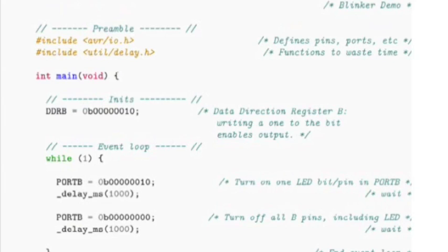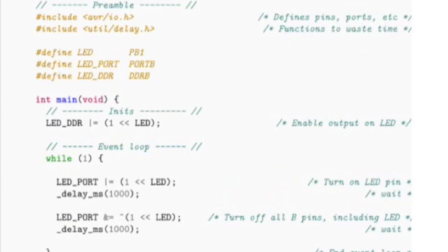So the first thing you want to do is use some defines to abstract away from where the LED actually is. So I always do this when I write new AVR code. You should too. It's like a hardware abstraction layer, but real small. Define LED as PB1 up at the top of those define lines there. Tells you that you've hooked your LED to PB1, which is awesome. Now you know how the schematic should look, but it also means that from now on you can use LED wherever you want to talk about what you're doing to the LED, and it instantly makes your code more readable.